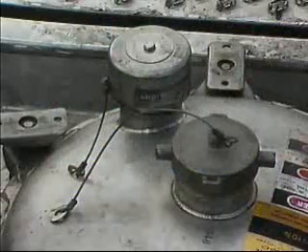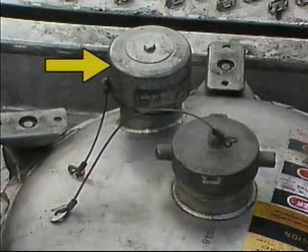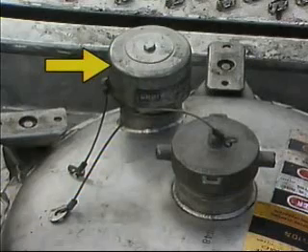Changes in pressure can also affect the handling of a liquid. For example, during loading and unloading, a vacuum may develop inside a tank. If this happens, the tank may be crushed by the air pressure outside of it. The development of a vacuum inside a tank is known as pulling a vacuum. To prevent a vacuum from developing, vacuum vents allow air into the tank to equalize pressures during loading and unloading.